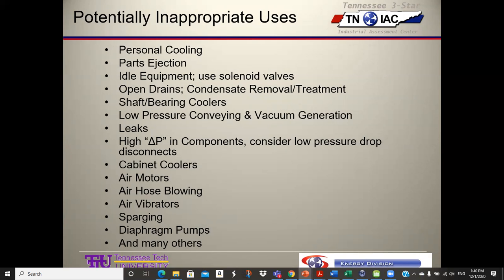So this is a way, if these lines are down a significant length of time, it's a way to avoid any leaked compressed air. Or you may have open blowers, that sort of thing, blowing applications down there, and that will de-energize those. So that's a good idea. It depends on the length of time it's down and how much you think it could save versus what the valve would cost and the control of it.